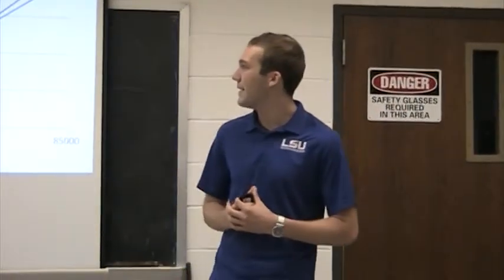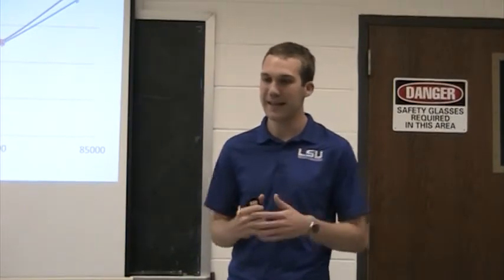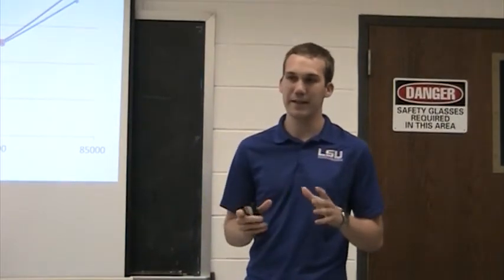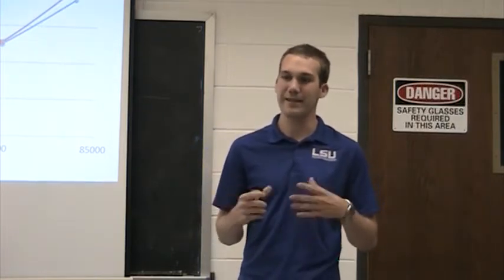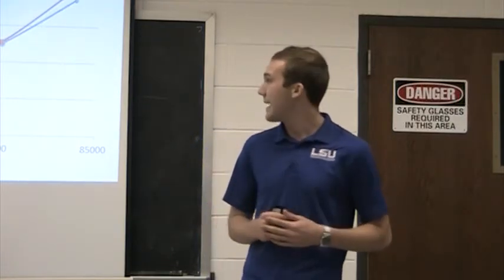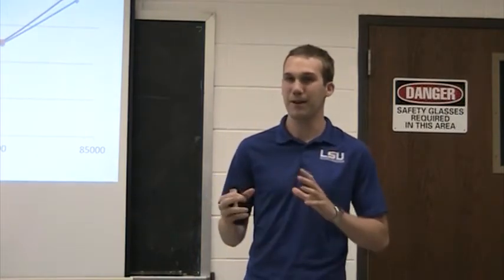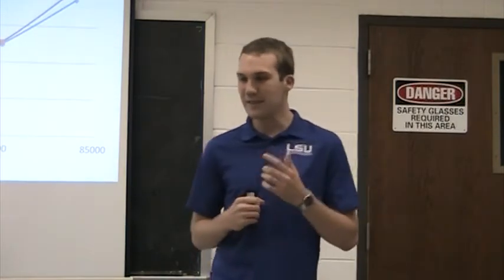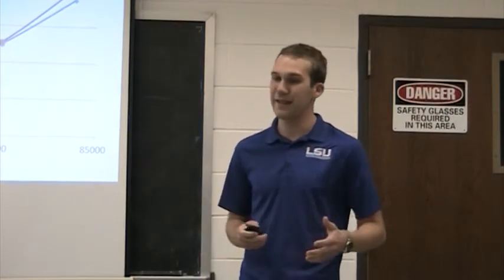This diagram is plotting the predicted exit velocity versus the RPM of the engine. Note that there's a couple ways you can do this outlined in the lab manual, one of which is through the continuity equation, mass flow, and that is represented by the blue line. You could also use stagnation pressure formulas to get the red line. They're very similar, and also note that they're directly proportional to each other.